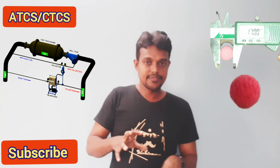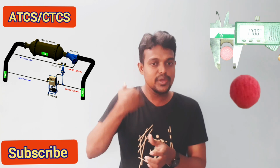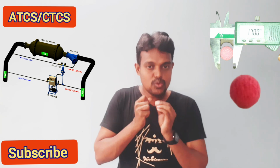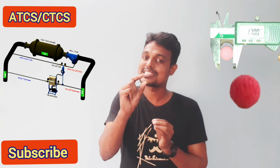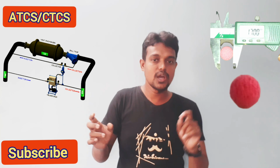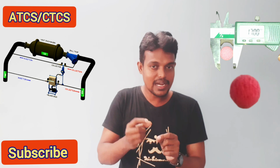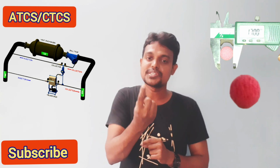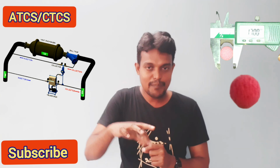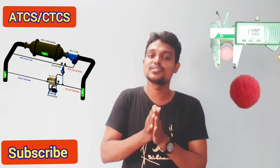Also, if your collection cycle and injection cycle keep going, like 100 cycles or 1000 cycles or 2000 cycles, you have to check the size of the sponge ball periodically. Once in 1000 cycles, you have to take out your sponge ball from your ball collector, and with the help of a digital vernier caliper, measure the size of the sponge ball. If you notice the sponge ball is less than 1 mm compared with your original sponge ball size, you have to replace all the sponge balls.